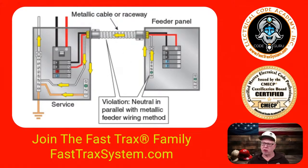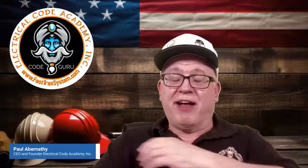I encourage you, if you want to fix this situation, go and look at 250.118 and see if the wiring method that you're using actually qualifies as an equipment grounding conductor. If it does, then you do remove this screw, isolate this neutral bus, all right, and then you're all good to go. And then you would be okay. So that's the whole purpose of that illustration.